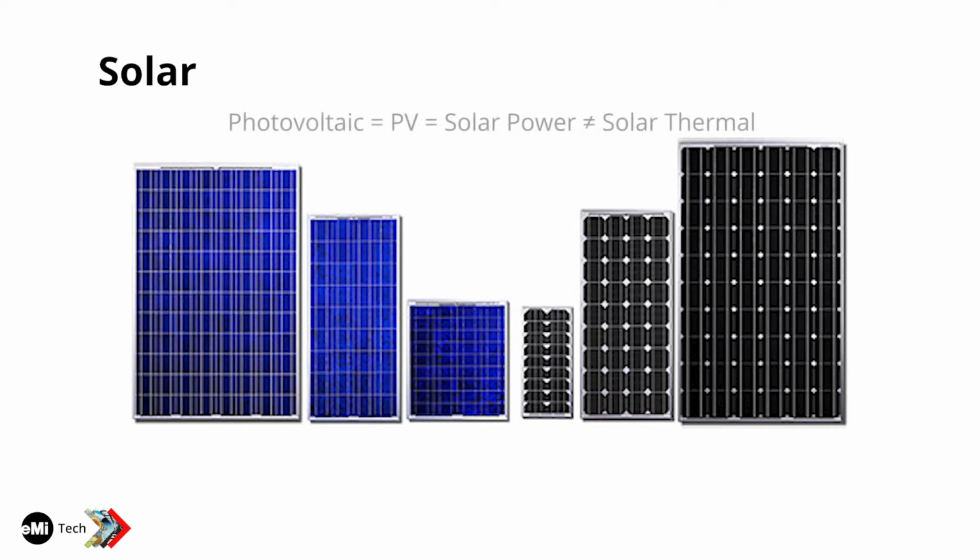These are solar power modules. For those who are not double E's, there is a difference between solar thermal and solar power, or photovoltaic. A lot of times there's confusion about this in the developing world. You'll come in and they'll say, oh, we want solar, and they've experienced solar thermal, and that is out of our scope. We do have some worksheets for it, and I think sometimes there's no one who's covering it, so it's okay to ask your project leader for some worksheets to give some estimates on that, but that's not expected of you. The PV is all that the electricals cover: the photovoltaic, converting the sunlight to electricity. Solar thermal is just for heating water.